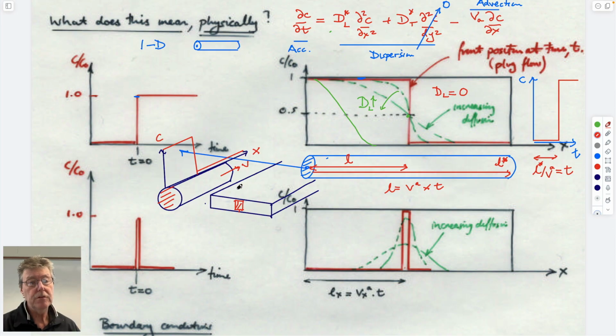But if you look in plan view at what this would look like, if you drew the contours of concentration as they traveled downstream, they'd look like this, right? This would be a low concentration. This would be the highest concentration here. And it would be a plume that kind of projects, just like smelling someone's aftershave. It travels kind of in all directions. In this case, it's biased that it travels downstream because the bulk motion of the water is carrying it downstream in this direction.